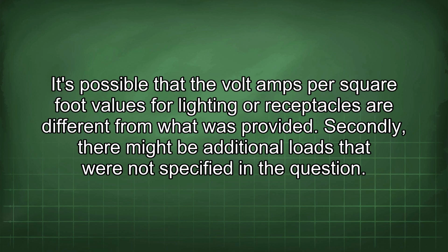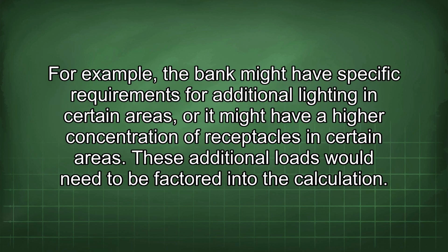Secondly, there might be additional loads that were not specified in the question. For example, the bank might have specific requirements for additional lighting in certain areas, or it might have a higher concentration of receptacles in certain areas. These additional loads would need to be factored into the calculation.